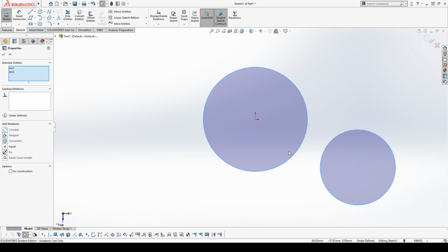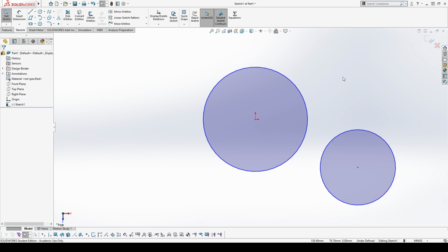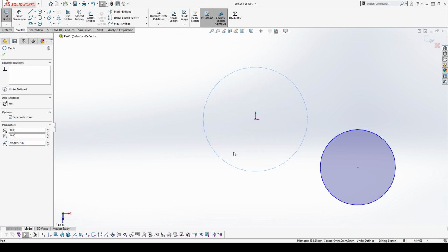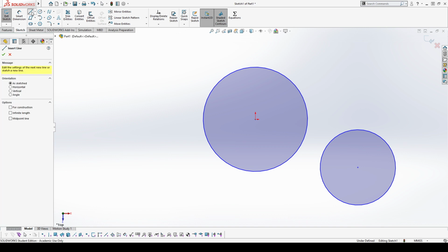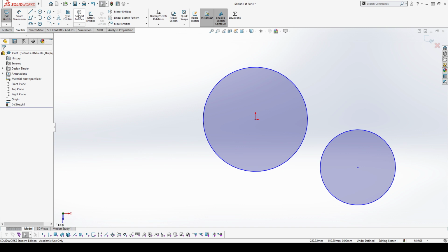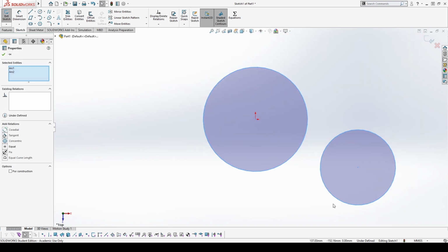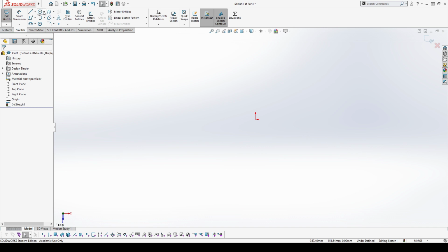Can you not have a construction for a circle? What kind of construction line would you have? The actual circle. Oh, you can make the circle construction geometry. Oh, okay, I didn't see it. Yeah, you have to click on the circle itself, and then you get the options. Yeah, off the left side. The only geometry that automatically gets added in as construction is lines. Lines gives you the option to be drawn in as construction, and then rectangles give you the option to add extra construction geometry. Yes, that's what we got there. And then under circles, it's just the circle and the perimeter circle.